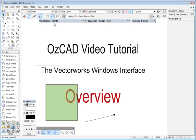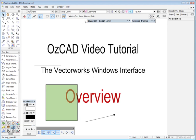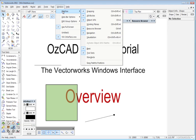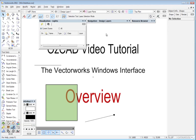So that should give you an overview of how the Windows interface works in Vectorworks. One thing I forgot to mention, if you do happen to close one of these palettes, so if I close the visualization palette, clicking this little button here, and I want to reopen it, and this applies to any of the palettes, if you go up to the window menu, then down to palettes, you'll get a list of the available palettes, and if they don't have a check mark or tick beside it, then just clicking it again will make it come back to the last saved position.